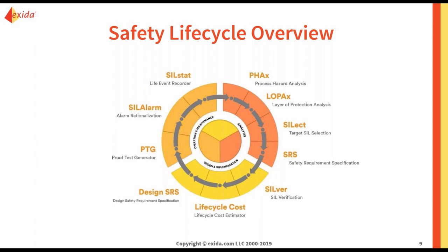Along with recording the proof test, you can do routine maintenance. You can record any device failures, and you can record demands on your process. And all of this data over a number of operating hours can not only validate your analysis and design, but give you data that you can use in the future for perhaps a greenfield project where you're putting in a similar process. So that's what SILstat does.